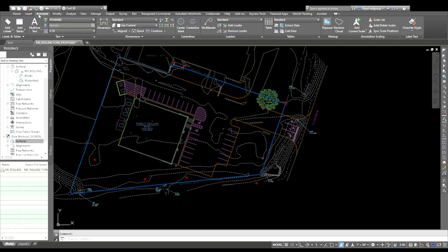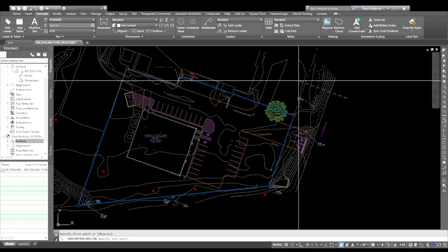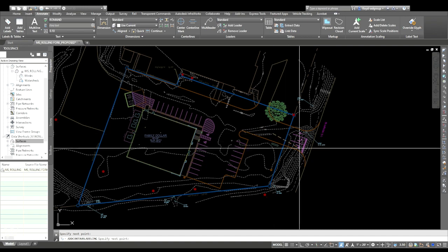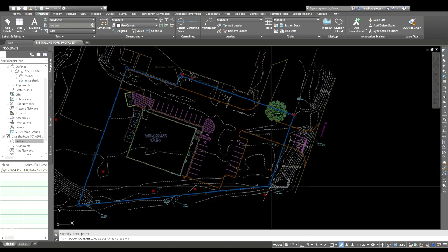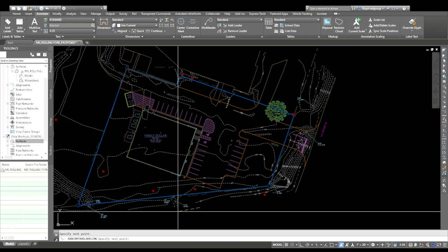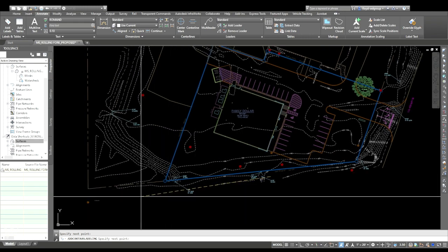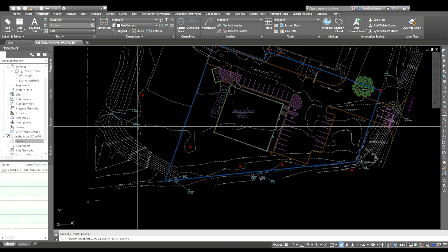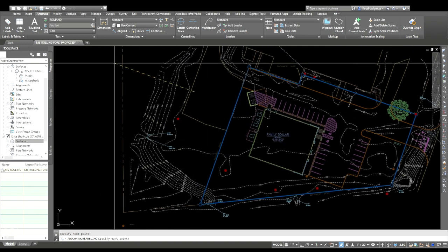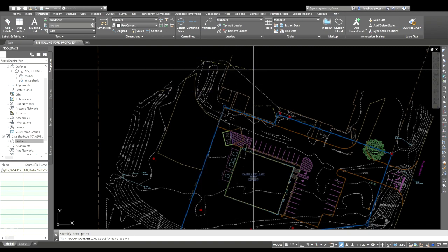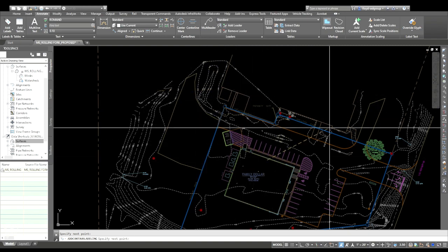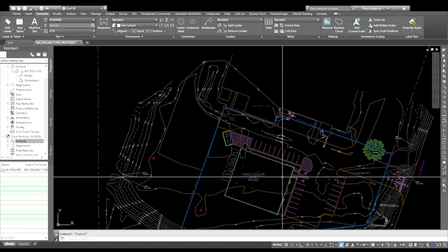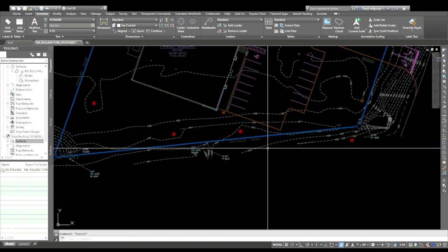see what they are. In an early video, I told you what I do is I go to surface, contour multiple for this drawing existing, because I really don't care. They don't have to be in around something or not around something or masked out or moved around, because they're just there. So when I look at that contour, I know what elevation it is. I'm not here trying to put them in and then come back and put other text from other areas in there or something. I just need to know what elevations they are, so I'm just going to put a bunch in here quickly. Okay, so now I've put them in there and labeled all my contours.